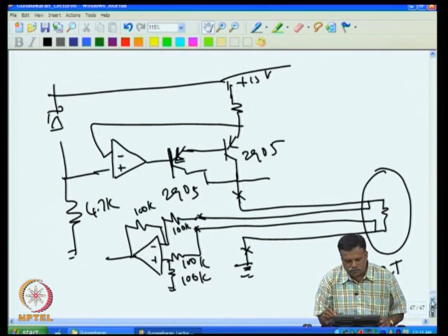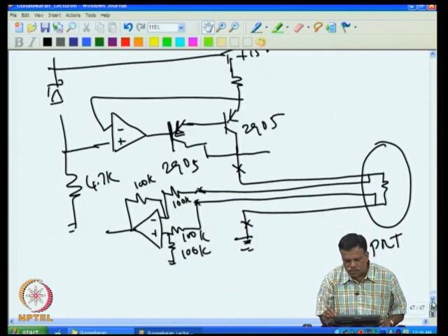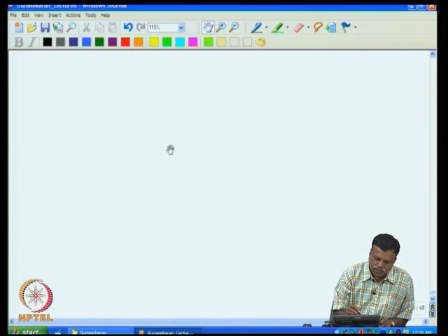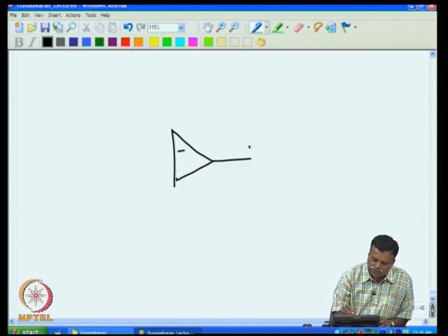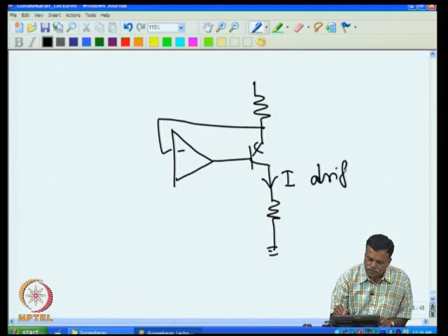Now, if you look at this, our Zener, okay, we will redraw the circuit for error budget purposes. So if I redraw the circuit and then try to find the error budgeting, I will concentrate now only on the simple resistance circuit. I take a constant current source and then a simple load. Find out what is the current error here with current drift. How much is the I drift? That is our main aim.